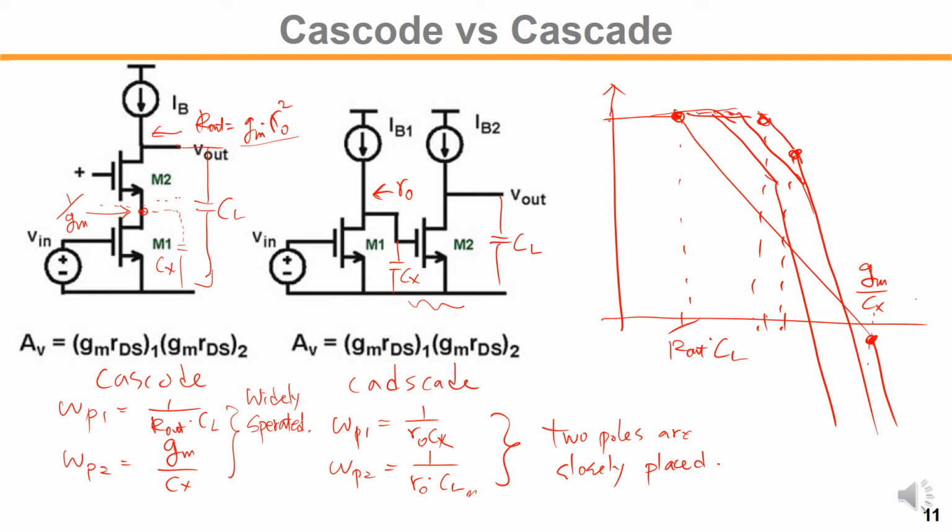So eventually it will have two poles within, so it will have a dip below. So in the cascade case, there are two poles below omega u, right? And at the omega u frequency here, it always has two poles. So this kind of behavior is very bad in a typical feedback system, feedback amp. It will deteriorate the phase margin in the feedback.